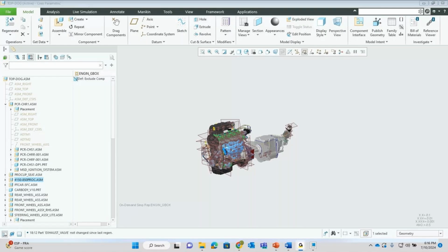So you'll have to force that. For instance, in my instance, I've only set them as automatic reps, so the master isn't there in any case. If I change those to display the master reps, then it will check it out and grab that information. If I want to update that external rep, then it will need to go and grab that as well. But it will never go to the top level unless the external rep is directly to the top level itself, like a skeleton or external geometry on that top level.